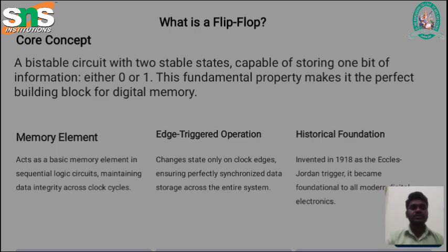First of all, we'll start with what flip-flop basics are. A flip-flop is a bistable circuit with two stable states, capable of storing one bit of information. That is either zero or one, the binary bits we are using. So for the operation of the flip-flop, on/off condition, 1 or 0, this is the mechanism we use in the flip-flop's working. This fundamental property makes it the perfect building block for digital memory.